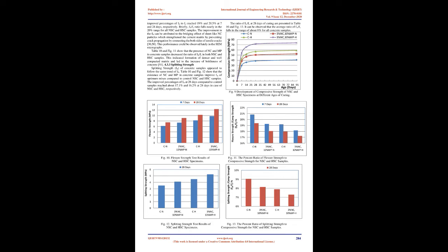12, 23, 30-36. While the decrease in FC of the mixes beyond the optimum ratio of NC can be attributed to the increase in its surface area, which produces more attractive forces between these particles, forming weak clogs. These weak clogs fill the pores of the concrete mixture, and consequently lead to forming a weaker hardened matrix. Moreover, the increase in surface area of NC particles leads to difficulties in the hydration process due to the insufficient amount of mixing water to coat all NC particles.